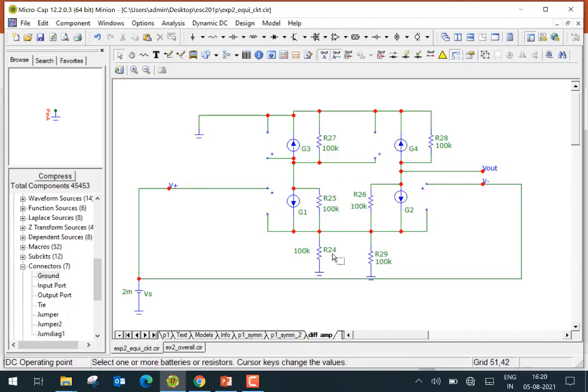So what we expect is that these two node voltages obviously are the same. And therefore, we could perhaps break the wire here. So let's keep the voltages the same. Note that the output is minus here, the output is there. And so let's break this wire here. Still nothing should change because this voltage and this voltage are the same, so there is no current flowing here. So let's break the wire here. Note that there's no change, still the same.